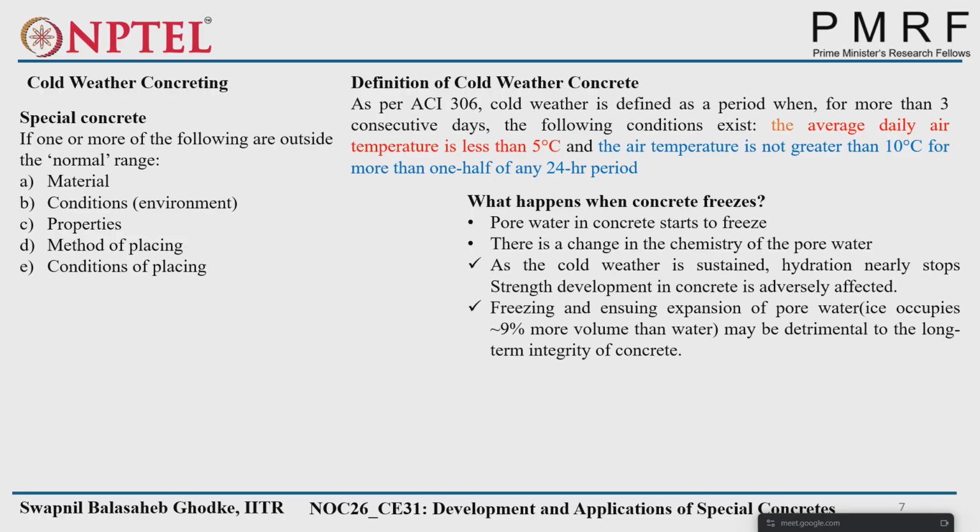So why do we have to worry about cold weather conditions? What happens if we treat it the same as normal concrete? Does it have an effect on the hydration? Any idea? Cold weather or hot weather? In hot weather, the hydration will be faster because of the temperature effect.